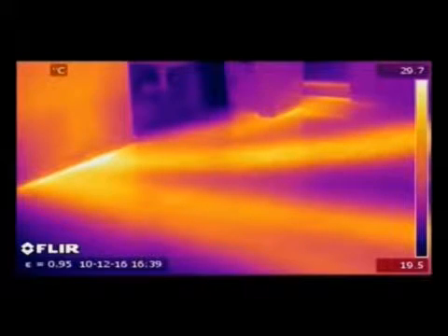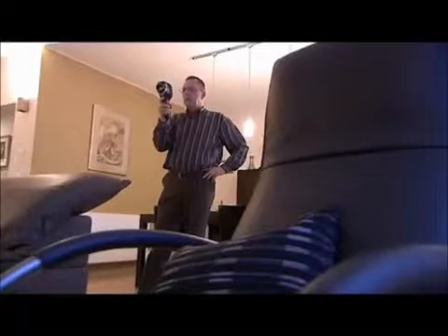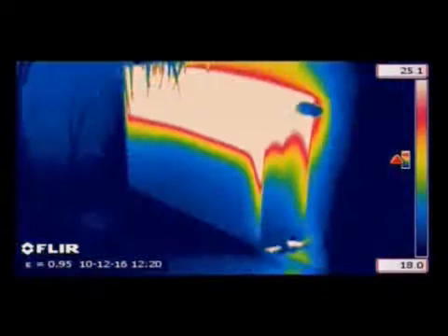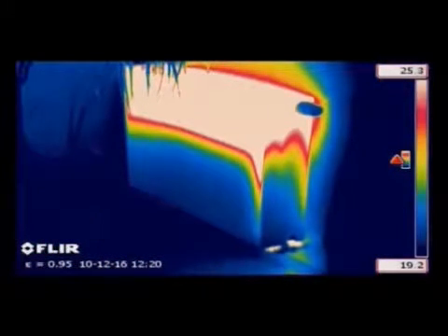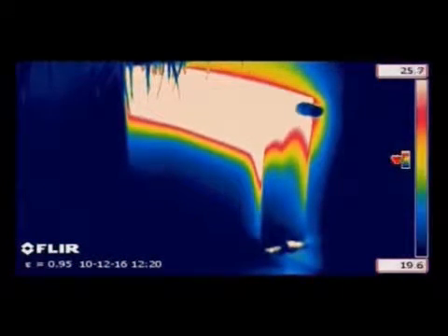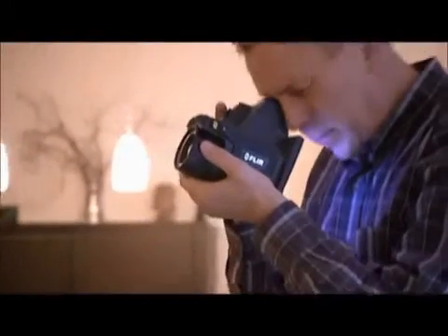Thermal imaging is an easy way for finding pipes and tubes and checking them for leaks. Heat from the pipes radiates through the surface and can easily be detected. A typical example is localizing leaks in underfloor heating systems. Heating and air conditioning systems can also easily be inspected with the help of a FLIR Systems thermal imaging camera.